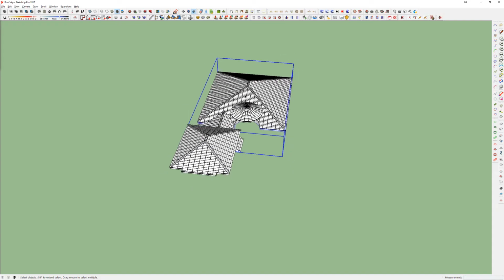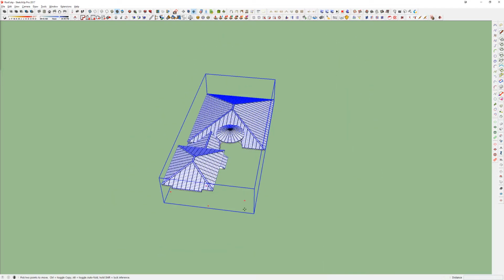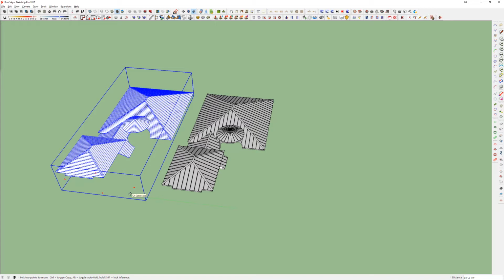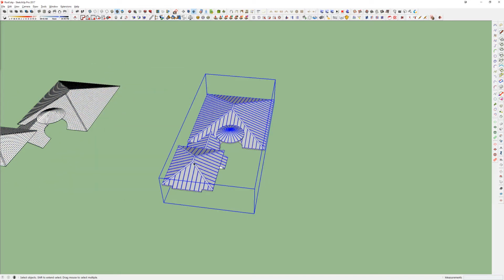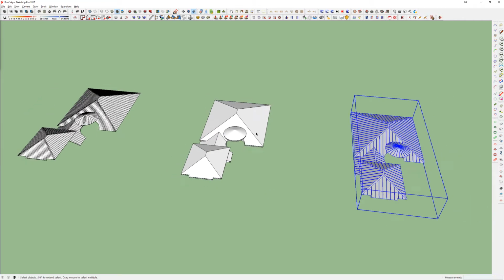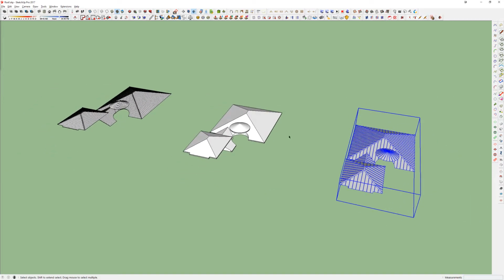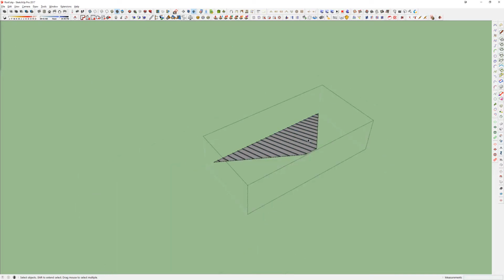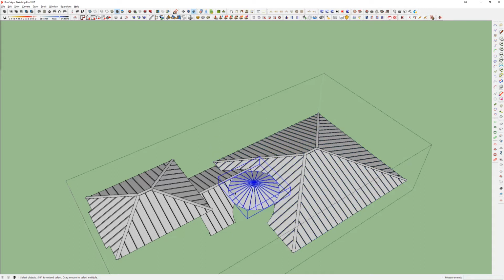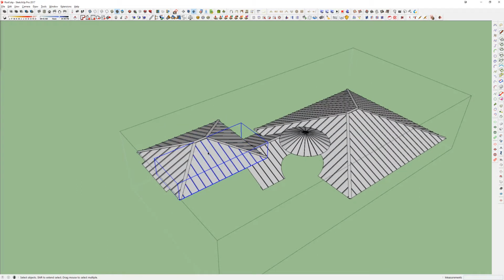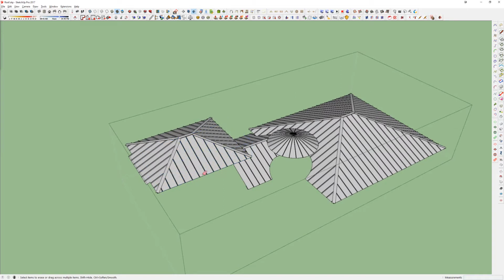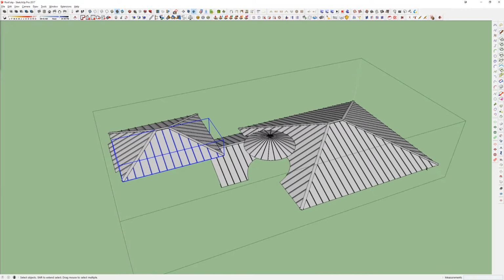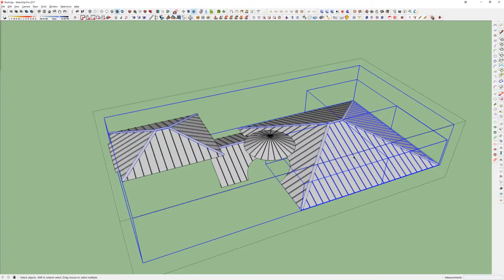So with that, I'm going to pull these roofs apart real quick. Here's my standing seam. Let's move this 100 feet, and we'll move this 100 feet this way. So partly the reason why I build these in their own sections is so I can hide the model. So I have this piece of roof, this piece of roof, and whatever pieces of the roof change, I only need to rebuild those pieces. So this isn't all one giant 3D roof. These are essentially Legos. And if, say, the back piece changes, then I just delete out the back pieces and rebuild those.